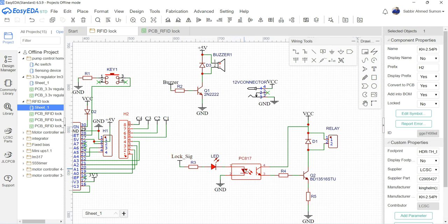When this LED is turned on, it emits light, and this is a phototransistor across pin number 4 and pin number 3. This phototransistor turns on when this LED is on. As the phototransistor turns on, this path is shorted, and I drive the BJT with this terminal.